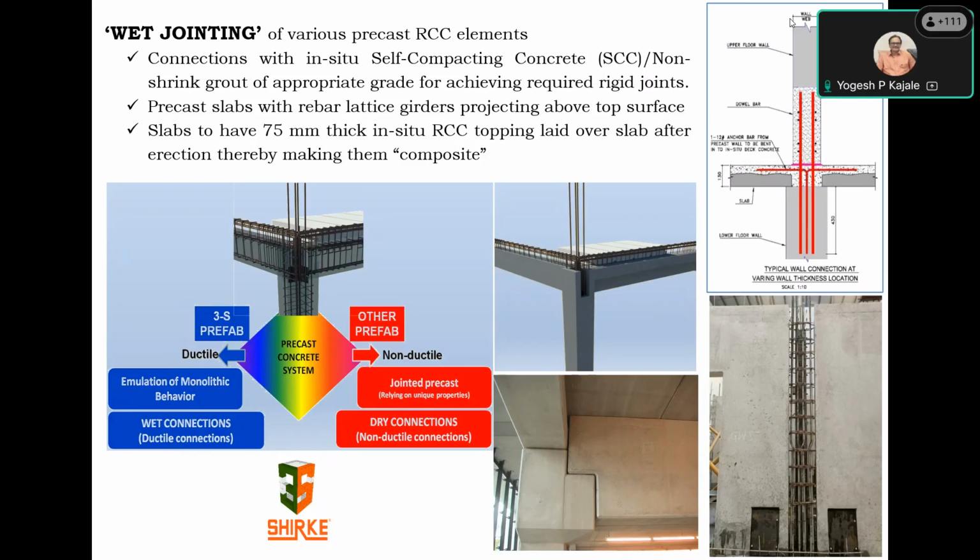As far as slab elements are concerned, the moment the slab elements are erected and the water is sprinkled onto the precast slab, if at all there are cracks, those cracks get visible through the wet lines, the water lines running along the cracks. Only visually can the cracks be inspected. There is no other way by which the cracks can be checked.